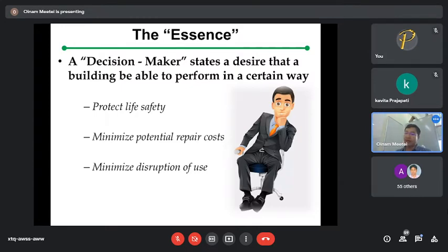I agree that after the disaster the structure did not collapse, but it was tilted by 20 degrees. Just to bring the structure back to the normal position, and the repairing cost, might be so huge. Sometimes it is better to construct a new house. Then what is the point of your performance based design? Performance based design means the structure should not collapse, but meanwhile the deformation should be at the minimum level. It means your repair cost also will not be high. That's the second point.